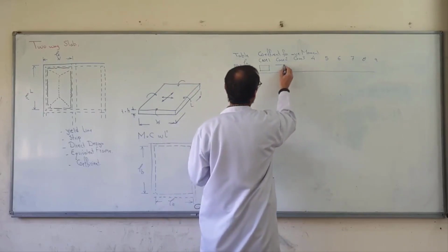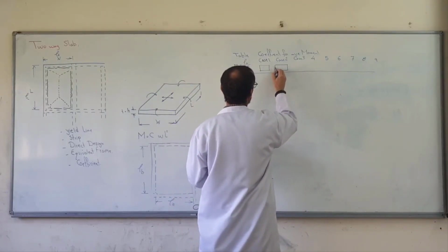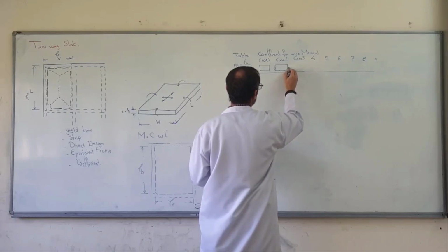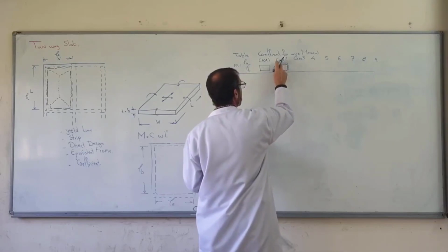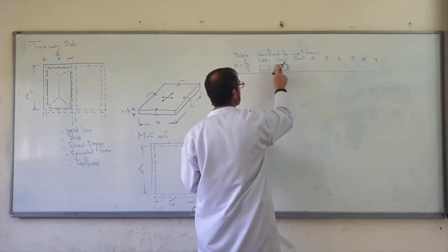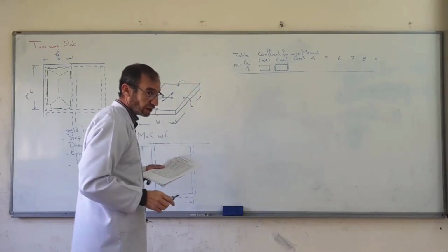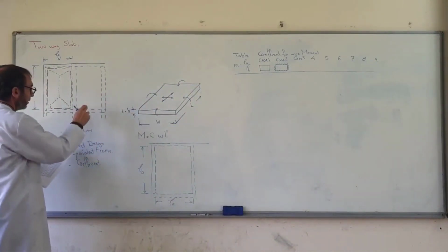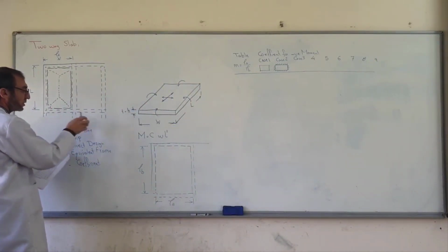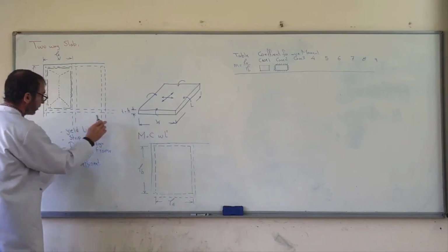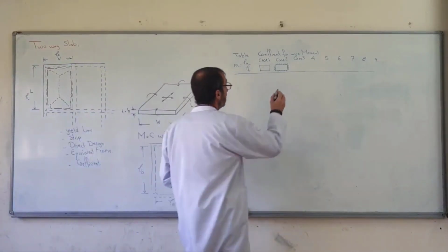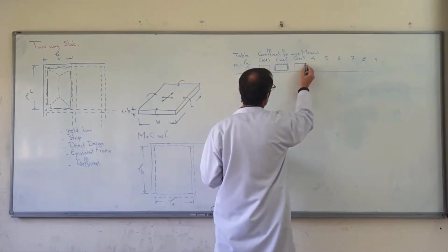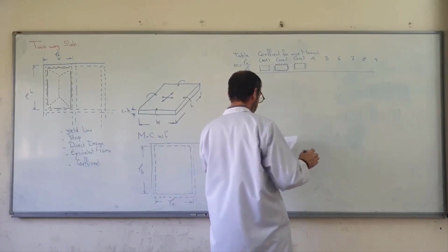Here we put this symbol in this direction. This means that it is continuous in this direction, like an interior support. Like this beam, continuous in this direction, or continuous in the other directions. Case 3, we have the slabs supported on 2 short directions.